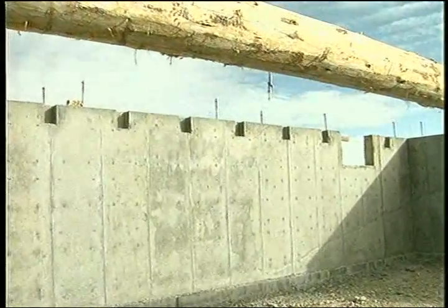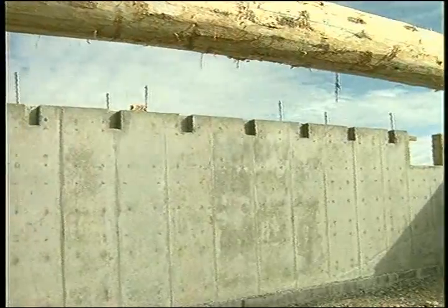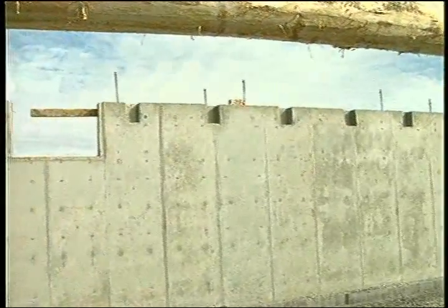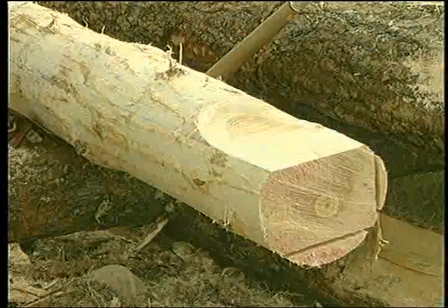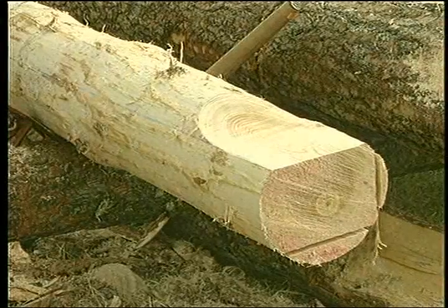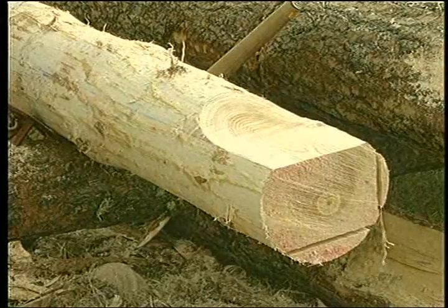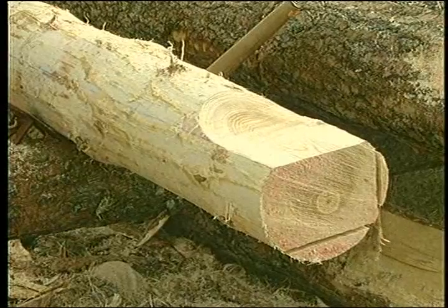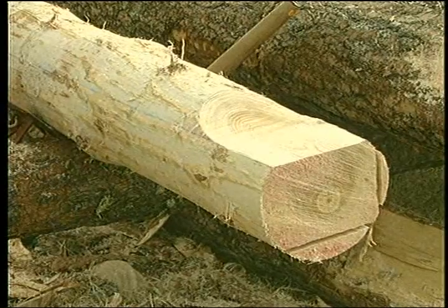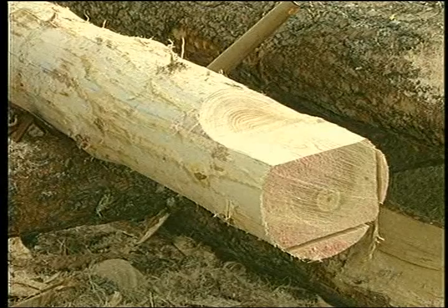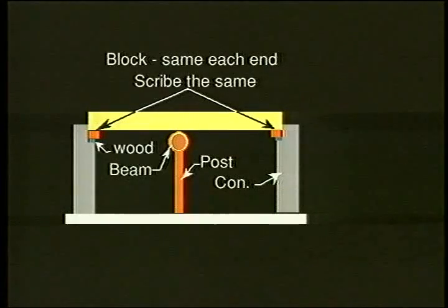Lower floor joists that are log and are to rest on a concrete ledge or pocket will be treated a little differently. First, square the end of the joist so that they are each the specified width and height. This might be 8 inches or 200 millimeters. Block up the central beam so that it won't deflect under the weight of the joists. Place the joist across the beams at its proper location and wedge or block the ends of the joist up until they are equal.